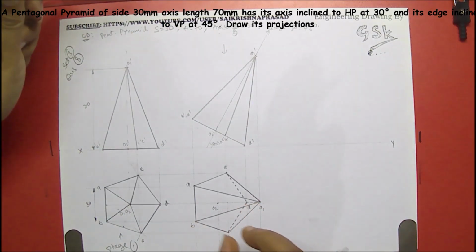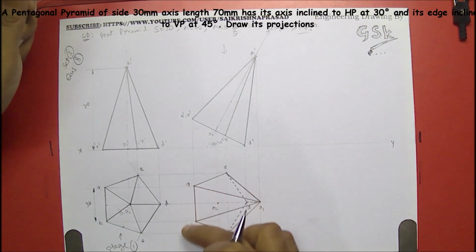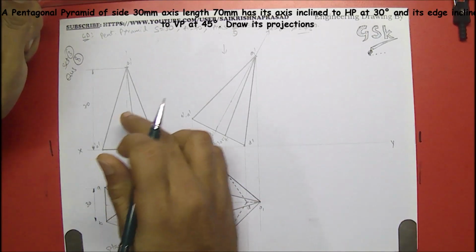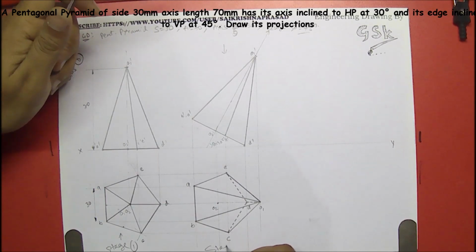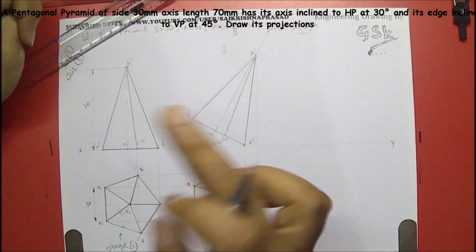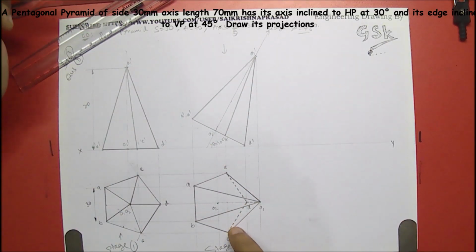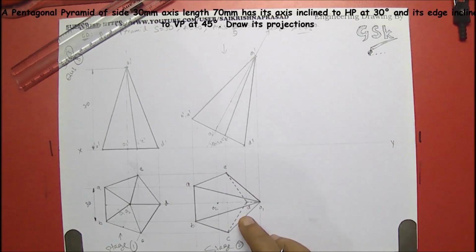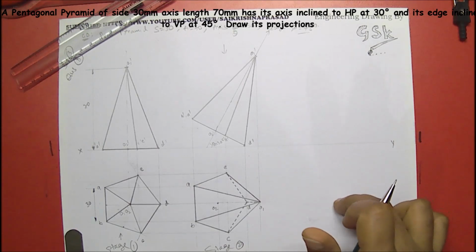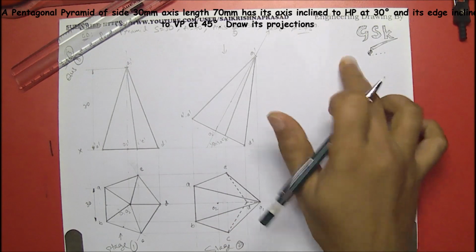Now you have to reproduce this figure over here with angle 45 degrees. Means I'll be taking this AB 45 degrees and reproducing the same figure over here. Stage 1, stage 2. In stage 1 you are producing the front view over here. In stage 2 you are reproducing the top view over here. Means this is the final projection of top view. With this reference, if you draw over here, you can draw the final front view. This is the top view, this is the front view.